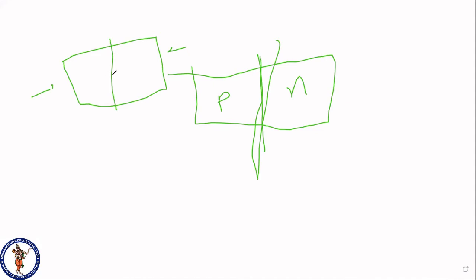At the junction, the barrier will be created after some time, and that is because of the recombination. Once the barrier is created, the electrons and holes cannot move from one side to another side, and this is the process of p-n junction formation, not this. The two n type and p type cannot simply be joined, and that is completely a waste of time. That's not the case.